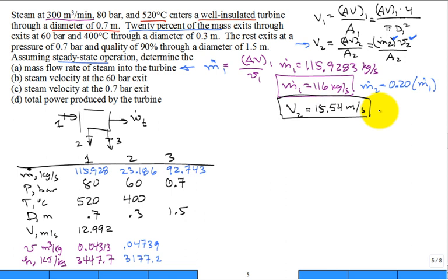Same way. So we would get the mass flow rate at 3. So V3, let me just say it's the same way. So I'm going to put the equation over here. V3 would be mass flow rate 3, specific volume 3 divided by A3. Okay, let's go to the table and get the specific volume at 3 and enthalpy at 3. But what do they tell us about state 3, which is a lot different than the other states?